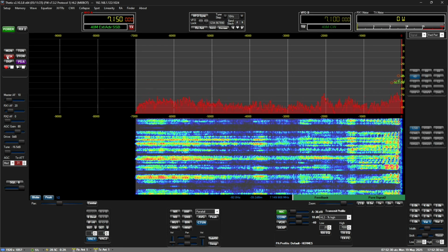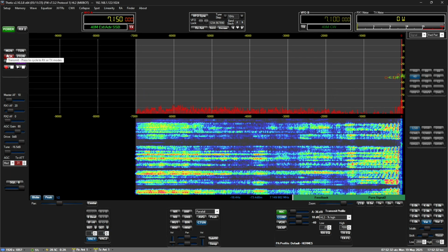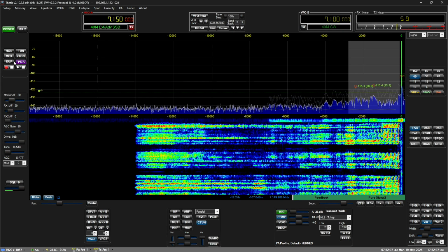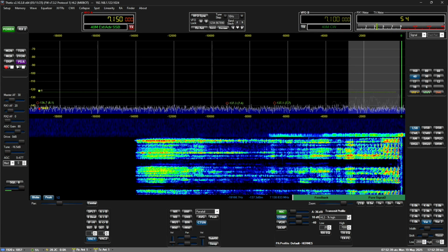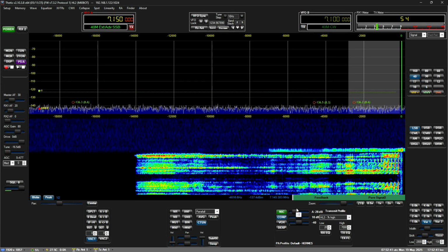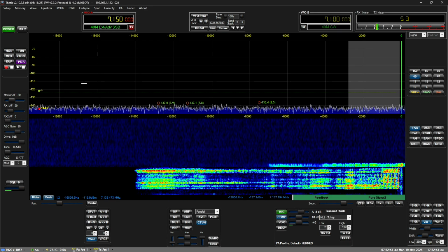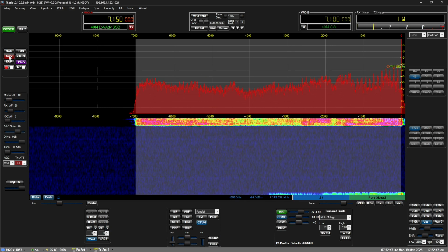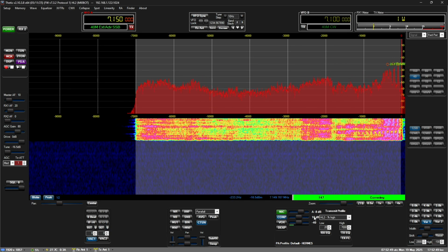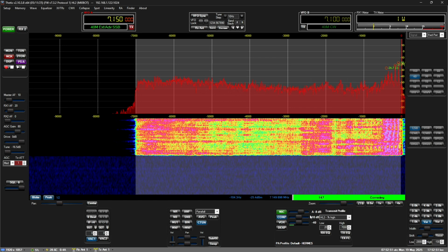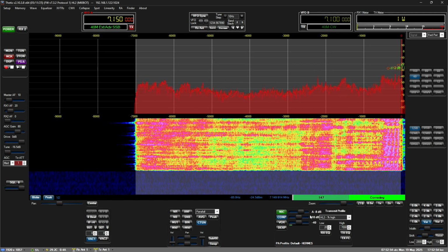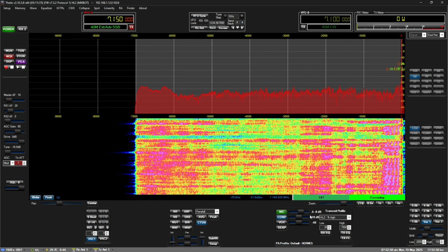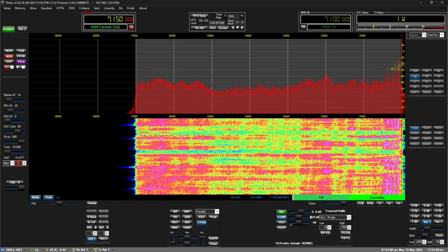And not getting enough power to enable the pure signal. What's going on here? It's the mic drive, probably it's not enough. Let's have a look. And if we go now, yeah, you're getting a little bit extra drive. There we go, pure signal is now working. You can see the range, it is very, very solid. That's because of the gain on the mic.